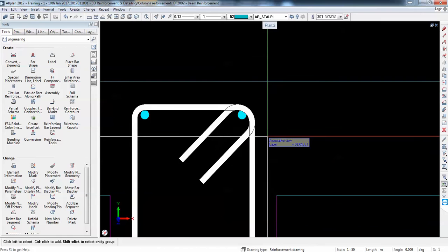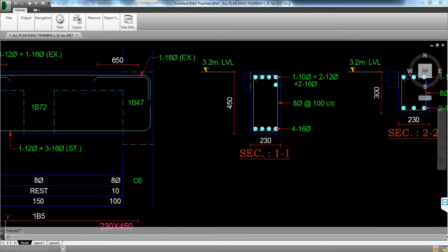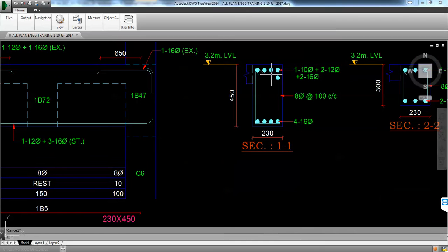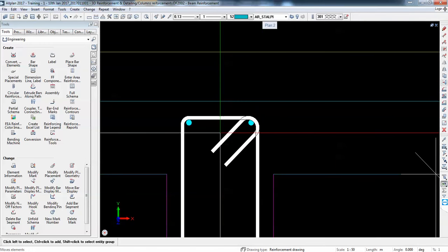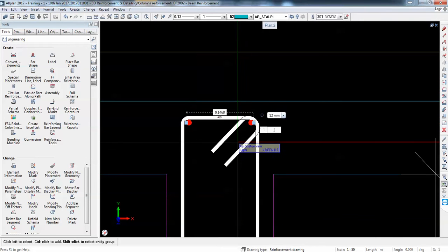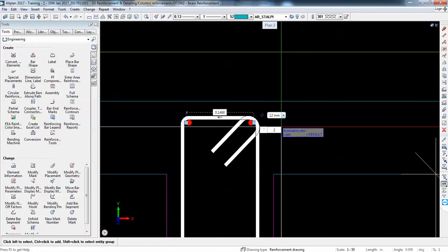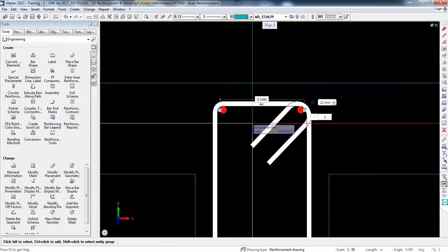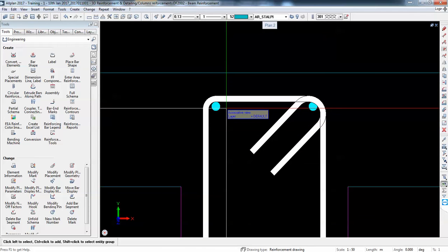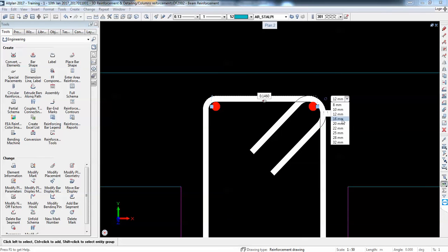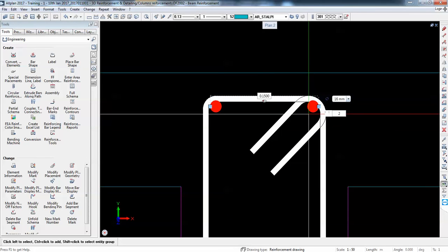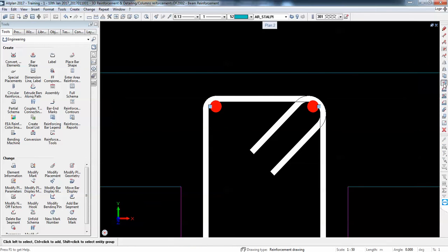Okay. Now I see what is here, and I will position the bar. One will be here, and one will be, I don't know, intermediate. So this was incorrect. It wasn't phi 12, it was phi 16. But this is no problem. I just hold the shift button, click on the bars, and now I can switch them to phi 16. That's all. And now I can place them differently to respect your drawing.